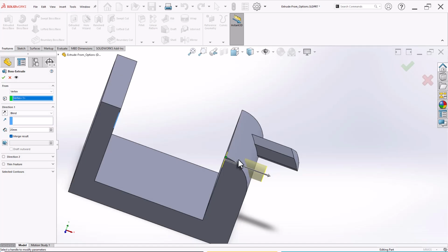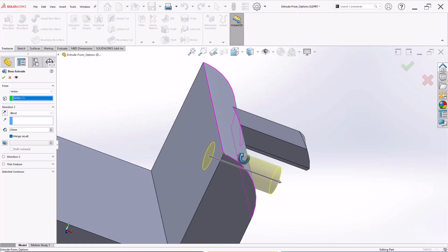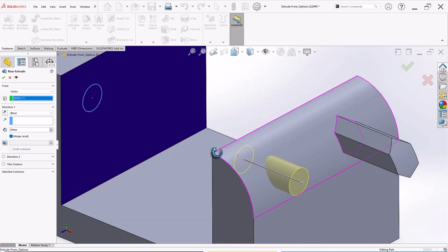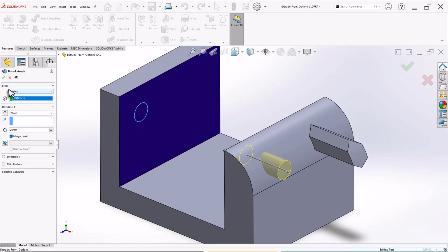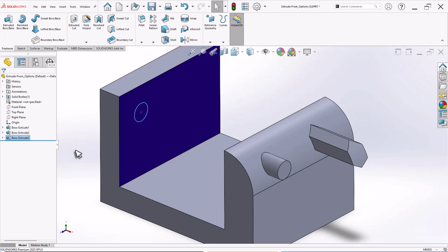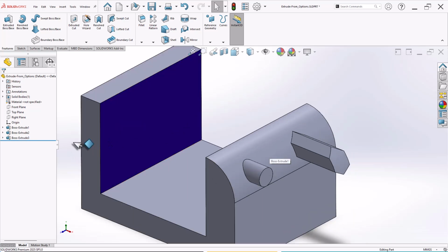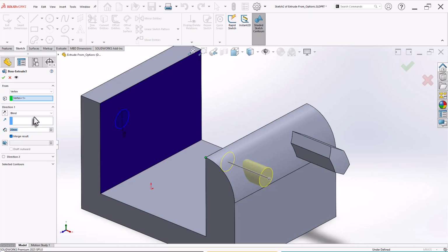Right? You can see very clearly. It is simply in line with the selected extrude. Now you can give the depth you want, let's say 20, 10, whatever, right? And click OK. Now let's try to edit the features. So select that feature.